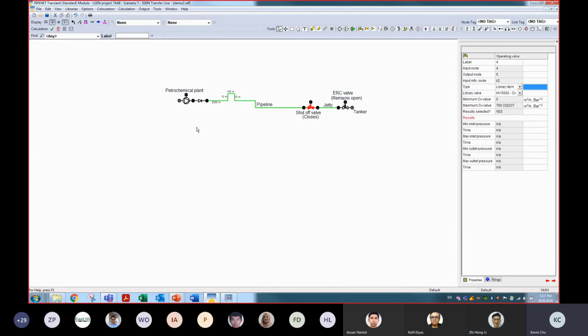I think the example that we show is water going to the overboard line. The reason it can form a cavitation there is because at the end of the overboard line it is exposed to the atmospheric environment. So when you expose the pipeline to the atmosphere, which means the pressure is atmospheric, then you can cause some vacuum there.